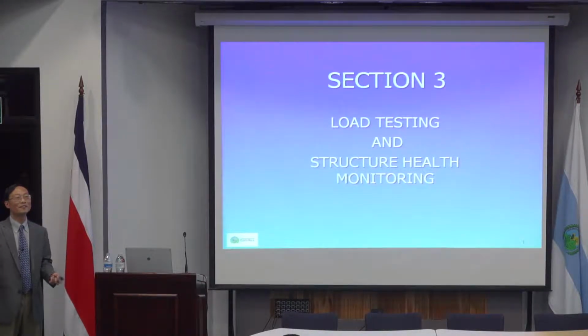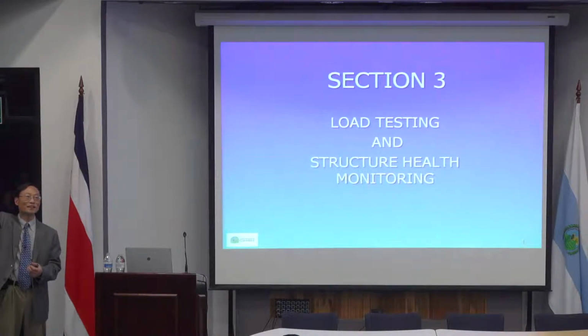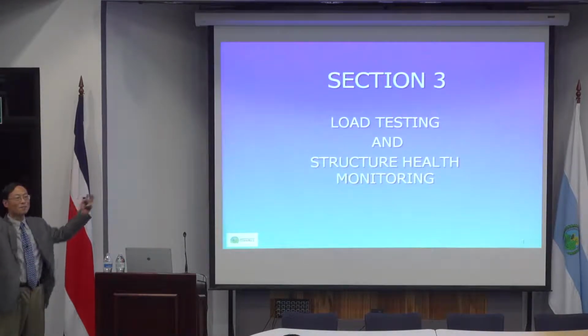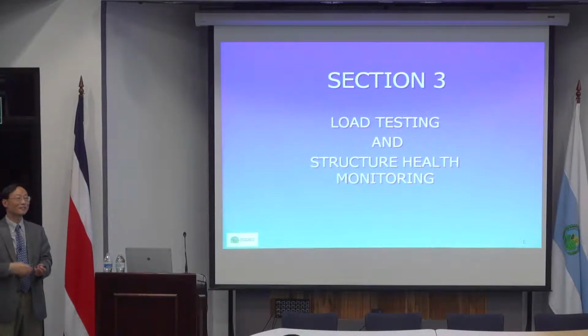But in reality, when you do the test, you can measure the stress or strain at each section for a couple of points. Once you have points, you can draw a line, and you will know where the neutral axis is. Most likely the neutral axis is not in the middle of the steel or concrete girder; it is much higher, so you may have a bigger component of concrete deck composite with it. And so normally you will use that as your finite element model.